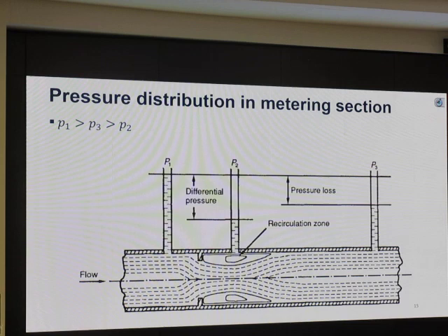Classic final exam question. We have the orifice plate. I give you the P1, P2, P3. Maybe I delete all this. Which point has what pressure? Okay, upstream. The orifice plate works by creating a pressure drop. Then we measure the pressure drop and convert that into flow rate, right? So, which point has the highest pressure?